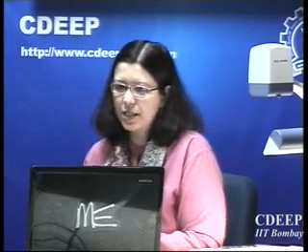Okay, so these were actually the most important characteristics, but there are more. As we continue, it will be boring if I just explain the specifications. Now you have an idea of what the non-idealities are. Let's look at one architecture and see how non-idealities affect its characteristic, and how we can calculate exactly DNL and INL for a particular architecture. That's why we start with flash ADC as a simple example and then see the effect of variation.